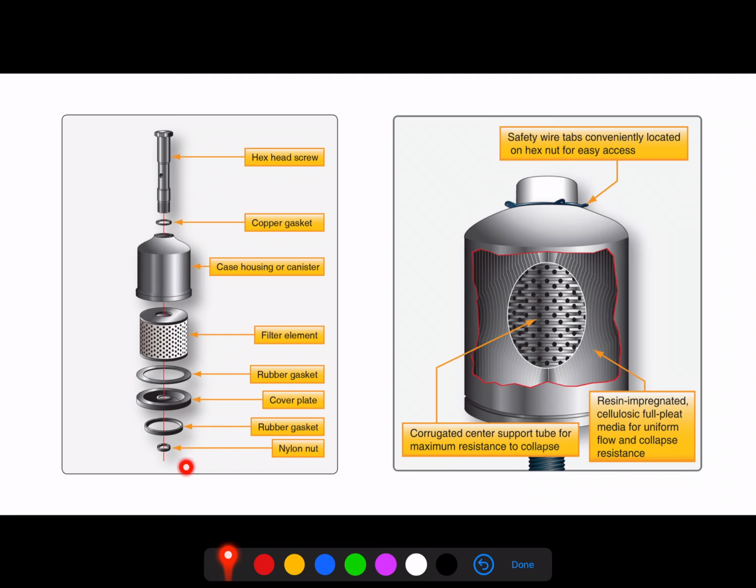Most often you won't see these with oil systems as much as you'll see them with turbine fuel systems and hydraulic systems where we use a replenishable filter element like this. Again though, the flow that we talked about is very similar. Under normal circumstances, we're going to flow up through those drilled passages that are outside of this threaded portion we see. The oil is going to be forced through the filter element into this corrugated center, and then it's going to flow out through that center portion, which is screwed onto the engine.